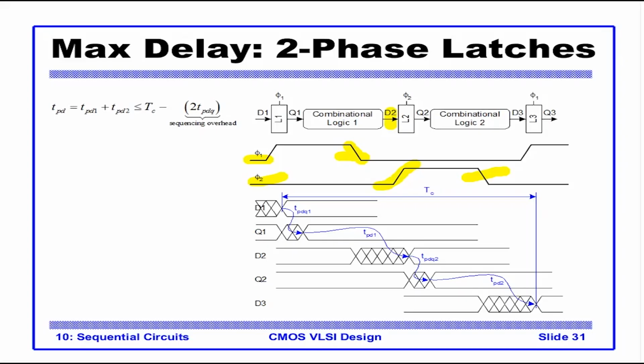Flip-flops are more preferred since sequencing is much more in control there. As you see, we use 2 clocks here. In a big design, let's say a design has 100,000 sequential elements, each driven by a single clock. This is a very common case where a single clock drives thousands of elements in a design, so there's a lot of clock overhead.